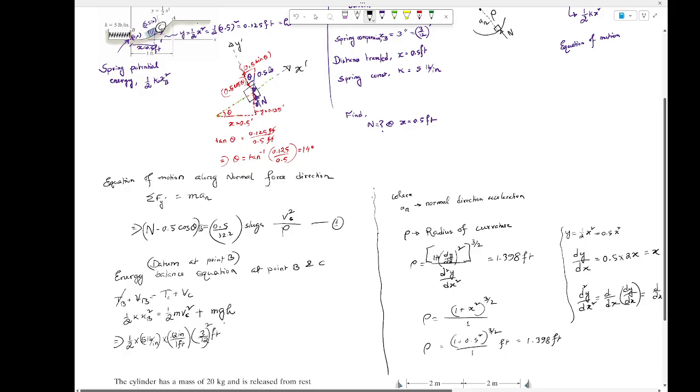You want to do a square here, right? So feet square, half of kx square, right? Or that's the amount of compression happen on the spring, by the way, when it's at point B, equal to half of, now this m, what is that m you want to write? Is it like 0.5 you want to write, or you want to divide it by 32.2? You must want to divide it by 32.2. 32.2, and then you have it slug, right? And then this v_BC square, and then plus this mg, the whole thing can be written as 0.5.